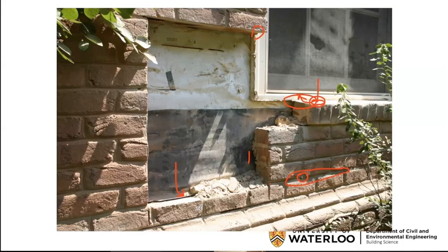The cotton was used so that the mason couldn't block the weep hole, because you could put mortar all around it, but it wouldn't be able to be blocked because you used cotton. But then they switched to nylon because, of course, artificial materials are better. And so now in this building, they literally had no effective drainage at all.